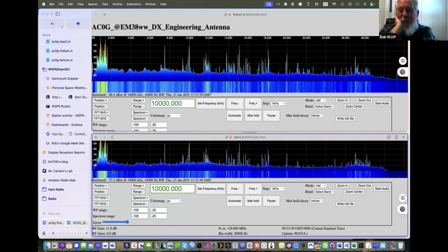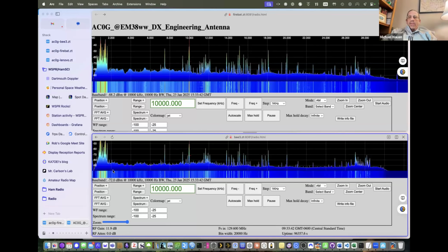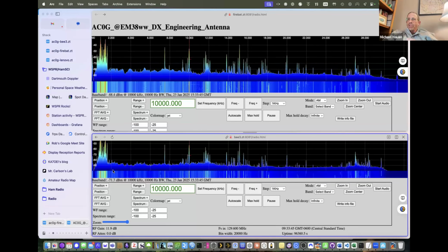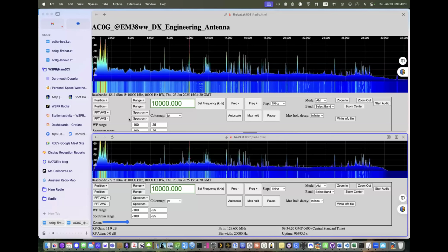Linear supplies work well too. Yes, if you can find them, the heavier regular linear transformer based power supplies are going to be more quiet than these little switched ones. And frankly, I had a couple that had the same distributor's name on them, but one was noisy and one wasn't. Not of the transformer type, but the switch type. You know, the ones that you get when you buy a Raspberry Pi, for instance. Now, some of them are quiet, some of them are not. You just have to find out. Anyway, the beauty of the spectrum is nice.